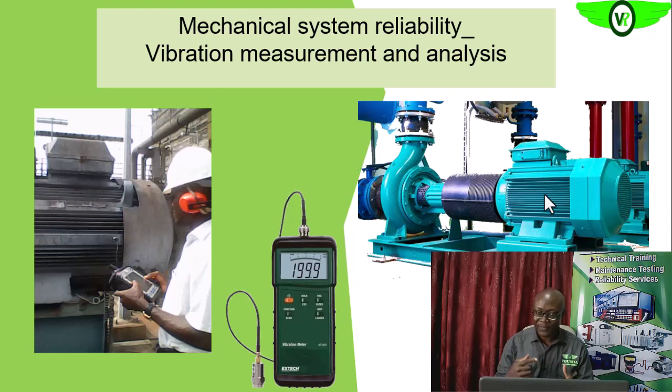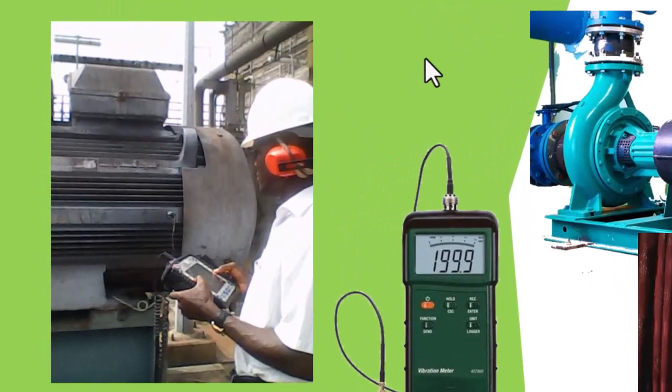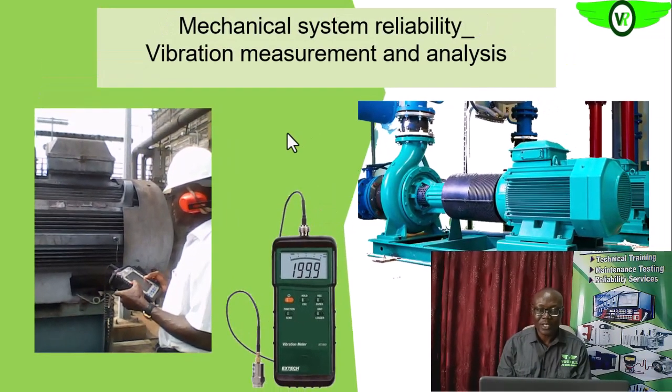Then the rotor itself, remember, it is expected that it will be rotating constantly. We also see some of the things that can affect it, like unbalance, that will affect the operations of the electric motor mechanically and thus the entire electric motor system. So one of the most notable means of looking at the mechanical integrity of the electric motor system is vibration measurement and analysis. Okay, so we know that as the electric motor is working, its component parts usually vibrate.